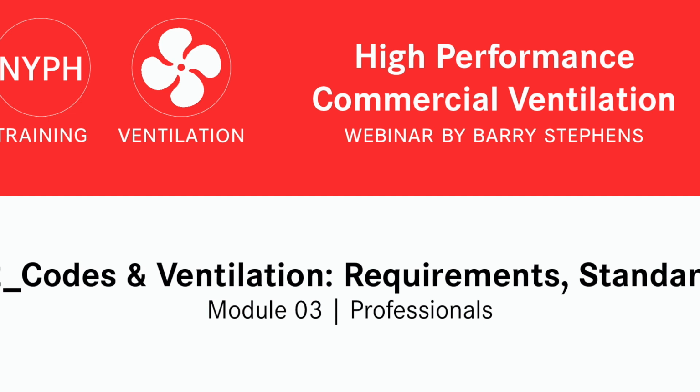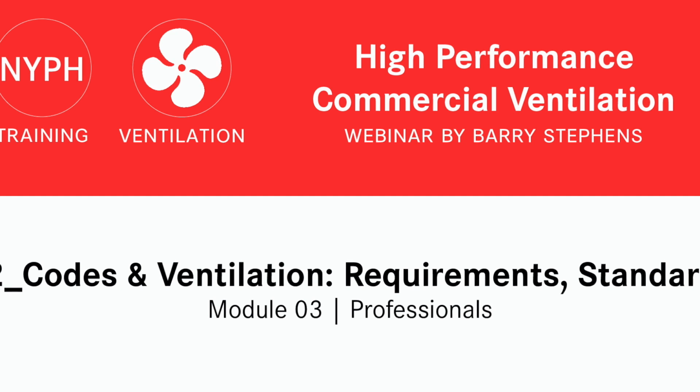Yeah. And then Andreas can correct me, probably, because I'm not an envelope specialist, but all my focus has been on the ventilation side. Think of it this way: the moisture issues in walls are when moisture is leaving the building through cracks and then reaches condensation, basically reaches dew point in the wall, and then you've got moisture in the wall, and that's a problem. In the wintertime, that is definitely a problem. As it cools on its way out, it may find its way to become water from water vapor somewhere inside the assembly.